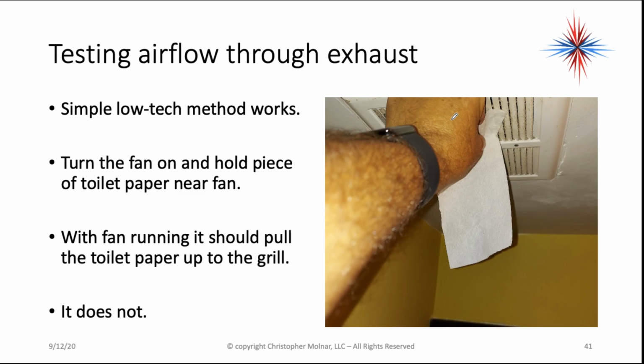Here's a simple low-tech method to check this. Turn the fan on and hold a piece of toilet paper near the fan. With the fan running, it should pull the toilet paper up to the grill. In this case, you can see it does not. This fan motor is turned on, and there's no air being pulled up here.